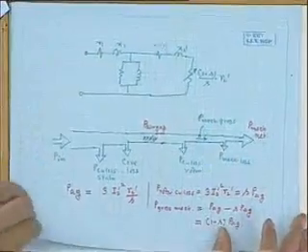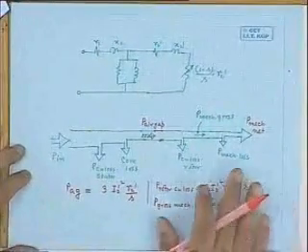this power flow diagram, of course, at a later stage will be slightly approximated whenever it is needed. Because see, I will tell you the problem only today. What is the problem in this power flow diagram? See, unlike a transformer, in a transformer, when you do the open circuit test, the secondary is open, no current is flowing in the secondary side, and the current drawn, power drawn, etc. you measure and get the values of RC, XM, etc., this parallel branch impedance. Now in an induction motor there is a problem.